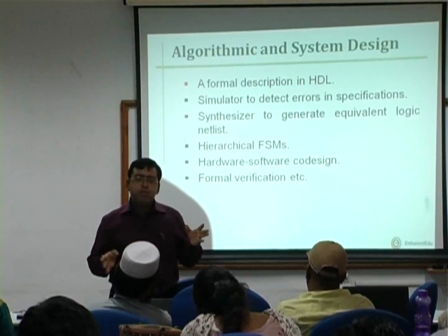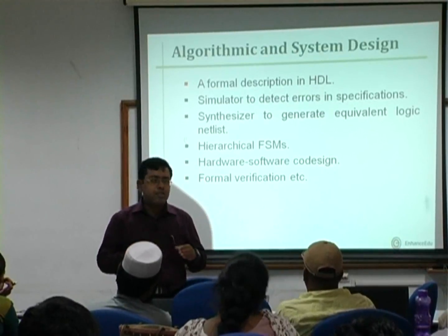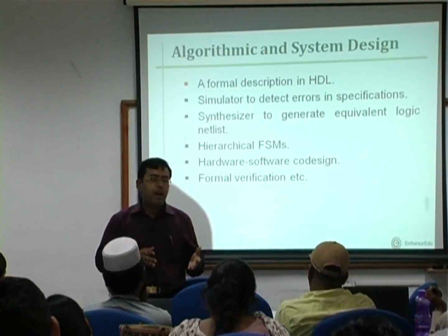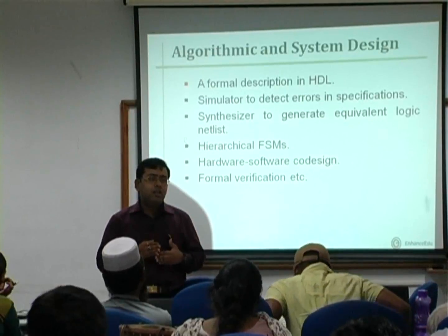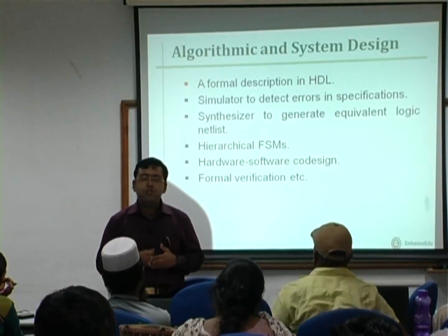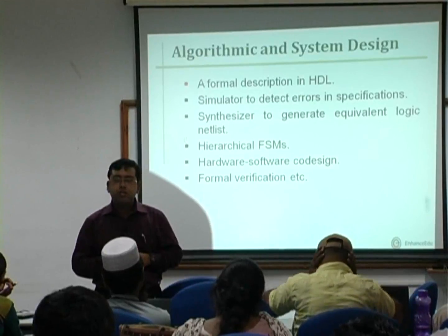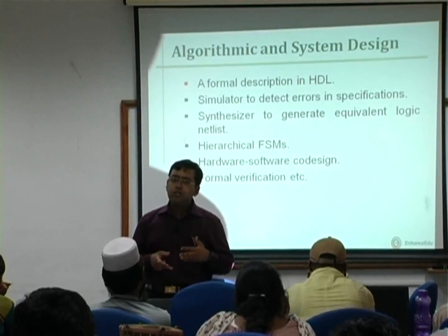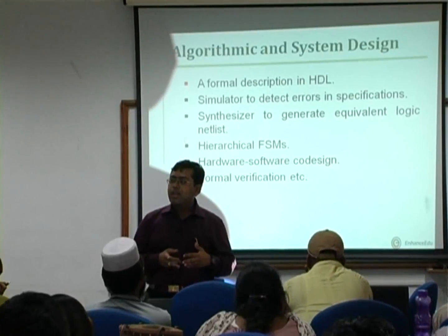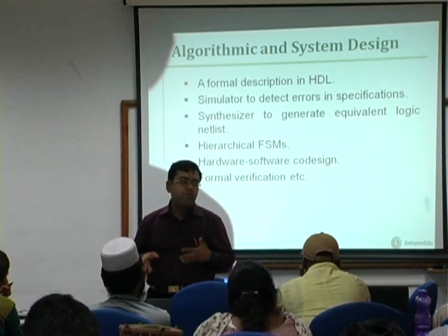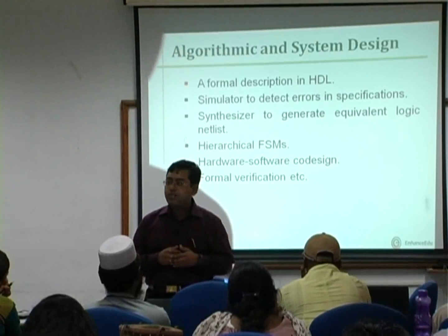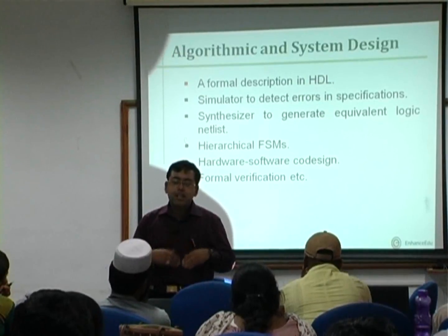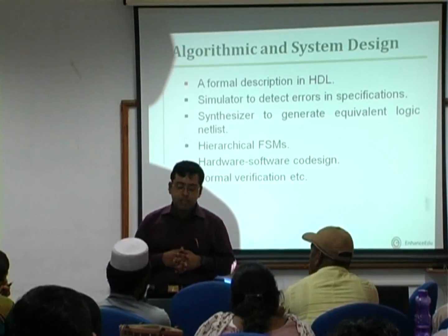So lots of optimizations take place when we do this hardware software co-design. In the case of hardware, we gain a lot in terms of speed of execution of the system, because hardware execution essentially means some circuits functioning, so you don't really need to write an algorithm that comprises a set of instructions which you go on fetching, decoding and executing, and doing iterations to accomplish the particular task.